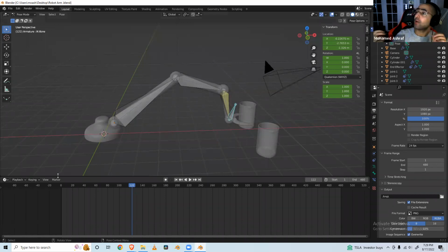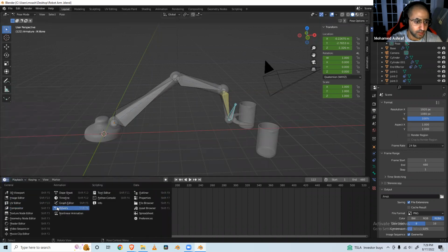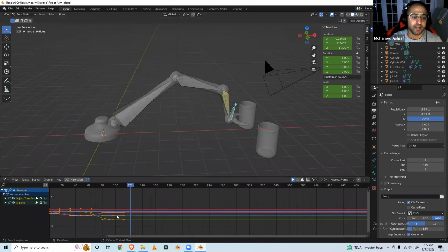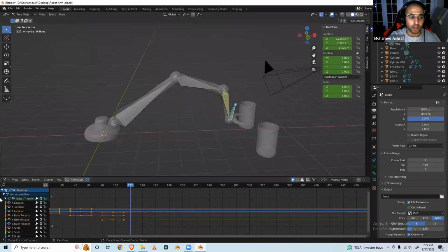And the way to actually visualize how the keyframes work and what everything looks like is to go into the animation and click on graph editor. This effectively gives you a graph of the motion paths, the values over time of every specific parameter. If you open up and drop down, you can see X location, Y location, color coordinated. You click on one and you highlight it. So it's a very, very granular view of what everything does at a high level. It's very useful. It's very powerful.